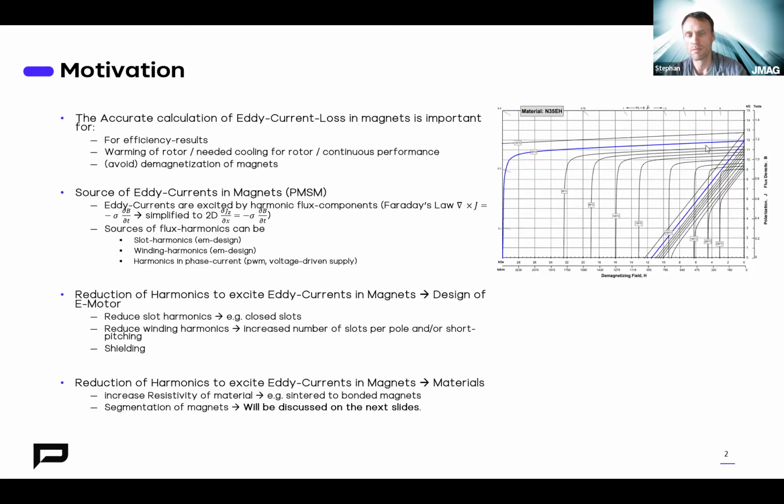But if you focus a bit more on the rotor side, for a PMSM the major loss components are inside the rotor lamination and inside the magnets. That's why the eddy losses on the rotor side are really important for the total loss on the rotor side.